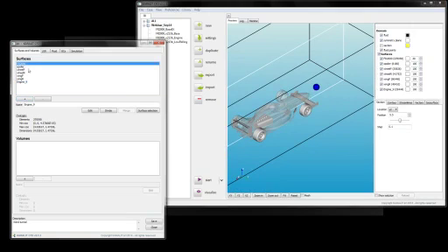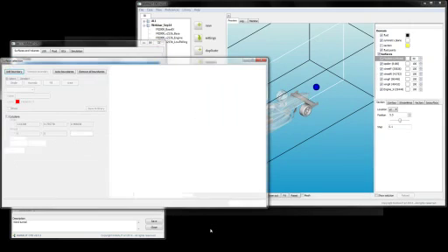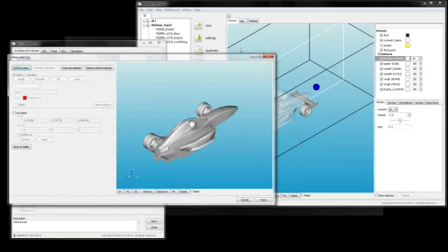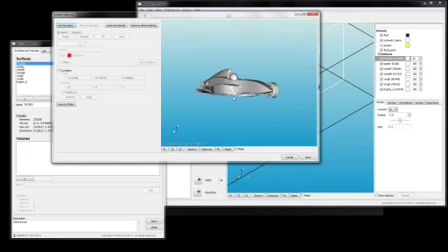What I would like to do here is pick up the outer surface of the car and open up those boundaries at the inlet, actually the belly of the car, to the external flow as well. The point being that we are tying the ventilation of the engine to the external aerodynamics instead of applying boundary conditions, which one would be uncertain of at that phase.